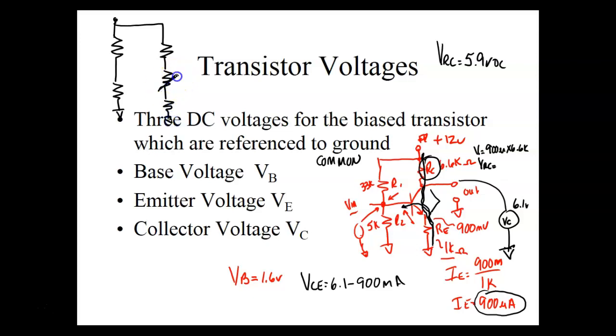The problem is that the transistor is acting like one of these guys right there. But I don't know the resistance of the transistor. And the way we calculate this voltage right here is, whatever voltage you calculate there, we take VB minus 0.7 for silicon, and that gives us that voltage. If we know that voltage and we know the size of the resistor, then we can calculate IE, and we assume IE and IC are equal to each other, right? You'll understand why we can do that.